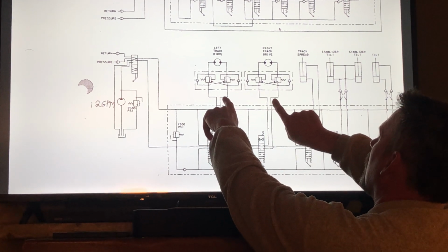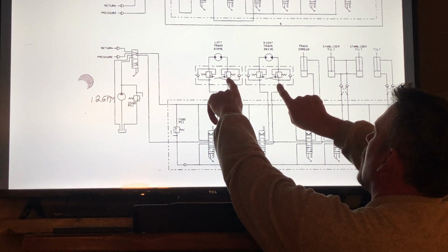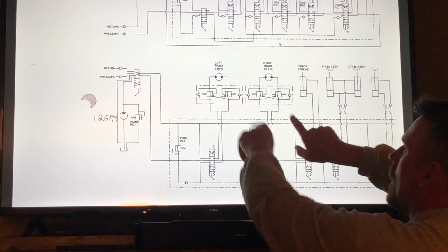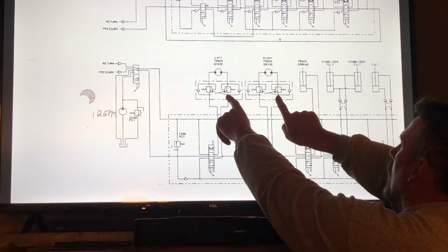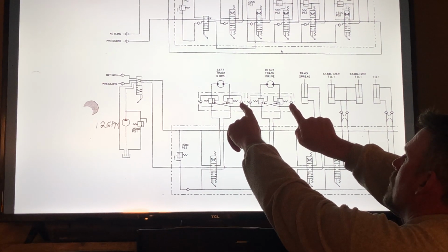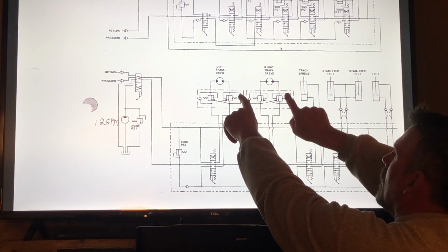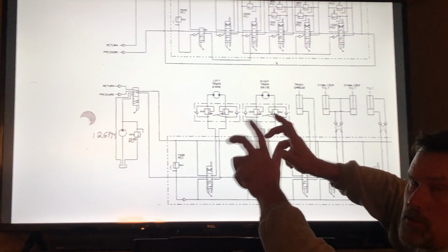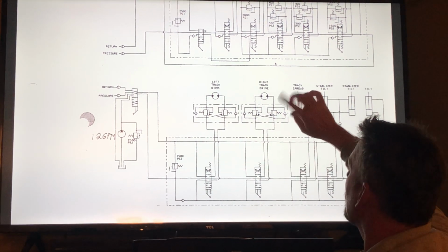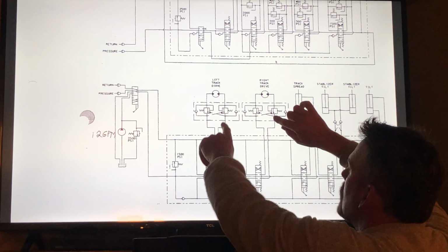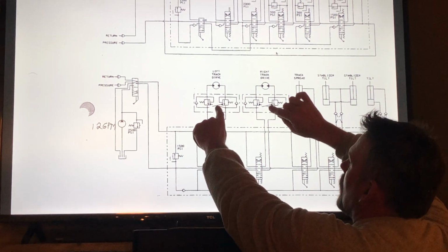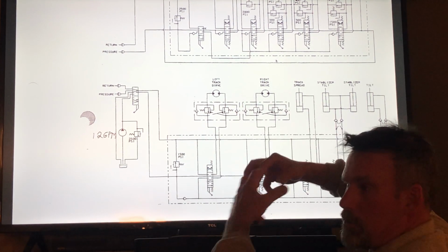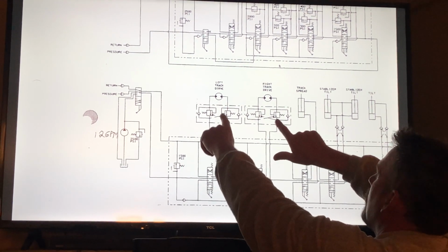So we go up here and the oil turns and comes along and hits this normally closed valve. Okay, so the oil can't get through that valve. So it scoots over here and goes through the check valve. Okay, and turns and goes here against each of the two motors. Okay, that's fine. There's also a passageway here. It's just a pilot line that goes across and no oil flows through it. Its pilot lines are just signal pressures. So that's full of oil.